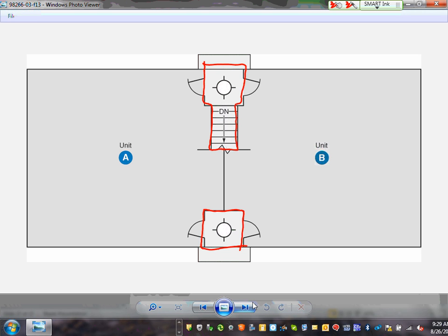So you have your option. You either have a separate panel that feeds, I have a light here, I have to have a light. I have a light here and here. I can't feed them from this apartment to that. So either I have a separate panel that feeds these lights and a couple of receptacles, which we will be doing. They call it the house panel.